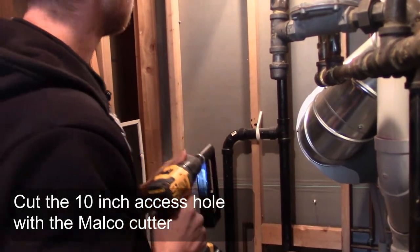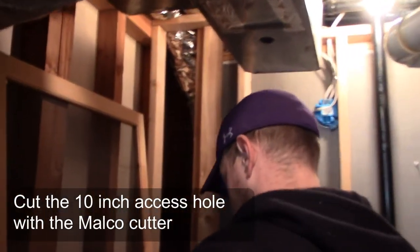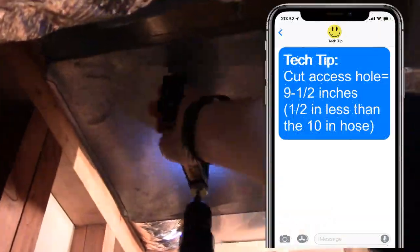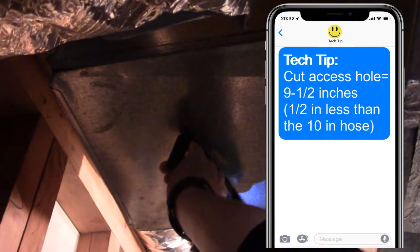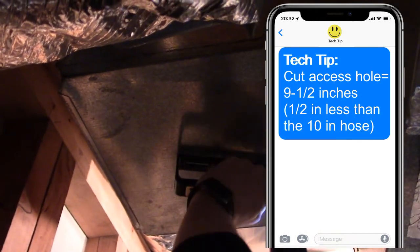Move in the vacuum collector, hole cutter, and everything you need to hook up in the return side trunk line. Cut access in the return side trunk line as close to the furnace as you can. Here's a tech tip. Cut your access hole 9.5 inches to best fit the 10-inch hose.